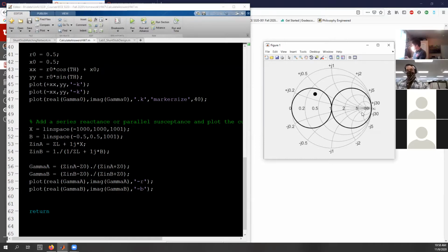Let me see that. And if you plot the normalized impedance, we're doing a low-high right now. We're doing the opposite. Correct, and that's the right circle. The left circle's the different circle. The 1 plus jX is the right circle, which you're talking about. But the circle to the left is not 1 plus jX. It's like 1 plus jB. Yeah. The 1 plus jX is the circle on the right. So if you are inside the right circle, that is a high-low.